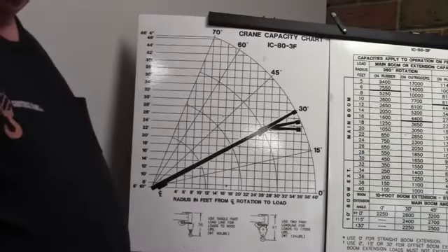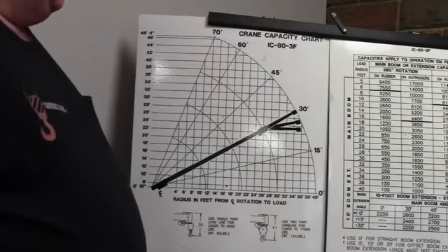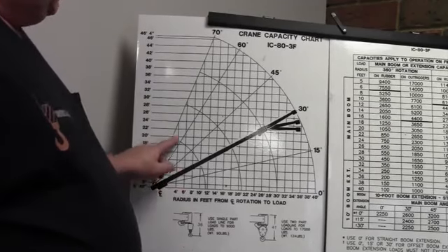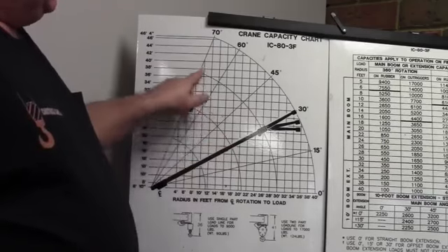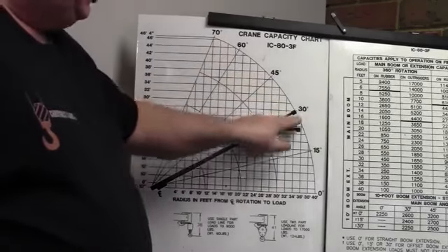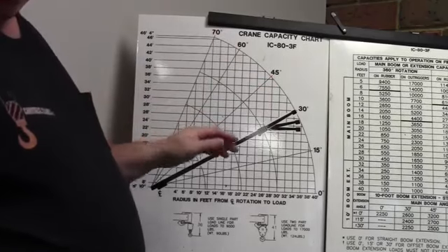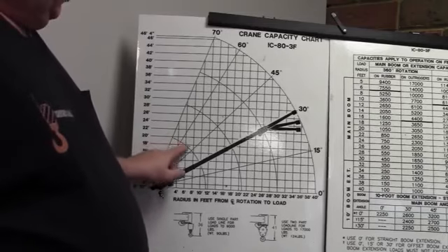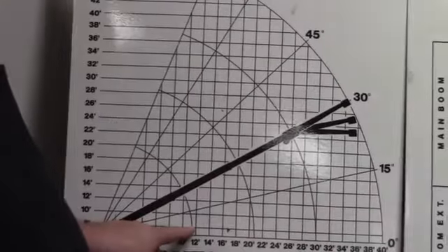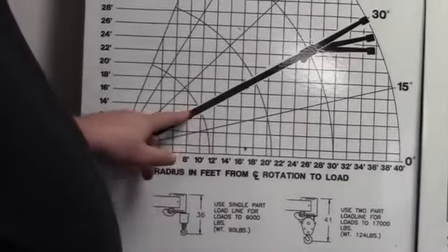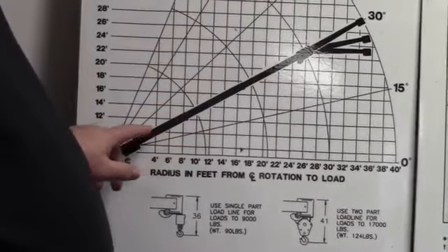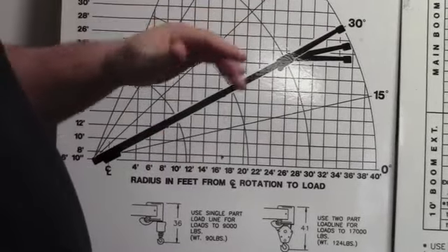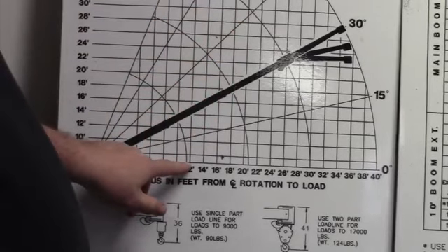This Broderson crane has a 3-section main boom with an available and optional 10-foot pin-on jib. You will see a series of arcs on this graphic representation that show where the boom would move at a particular length as you raise it to 70 degrees and lower it down to 0 degrees. This first arc represents the main boom only, completely collapsed. From the center line to the end of the boom, when the boom is at 0 degrees, exactly horizontal, is about 11.5 feet.